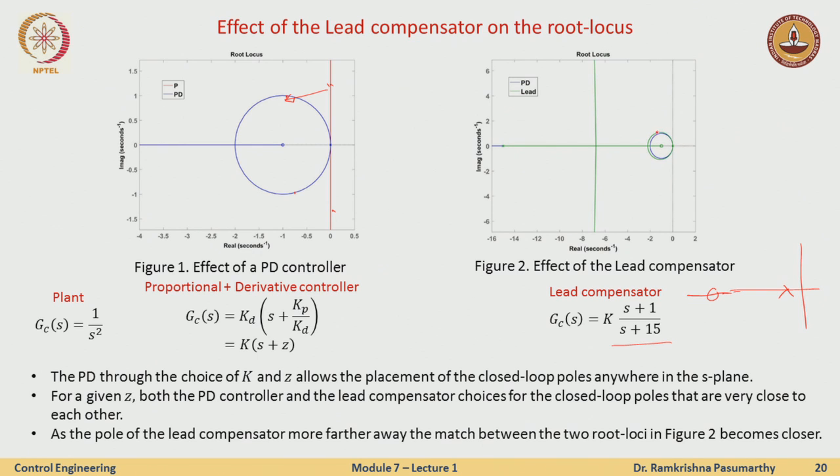The green line and the blue line are fairly close enough to each other, and again with some little adjustments here I can get my closed loop behavior to perform in a certain manner, right. So, what we conclude here is that the ideal PD controller improves the transient performance by pulling the root locus to the left. It also helps in increasing the relative stability.